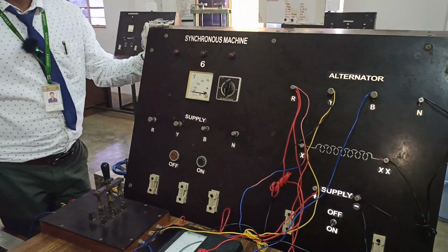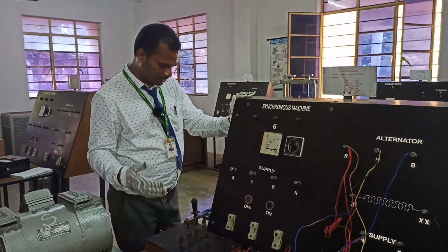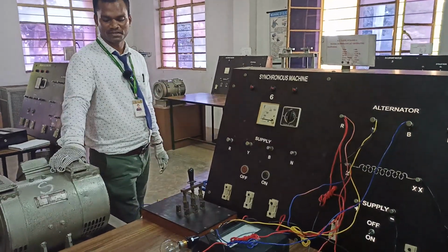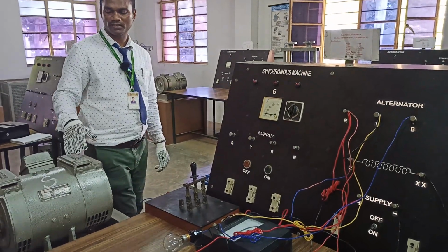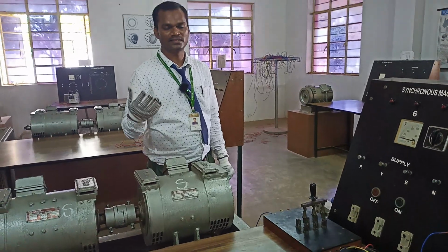In a further experiment, we will try to replace this alternator with a permanent magnet synchronous motor, and we are going to find out the regulation of this alternator. After finding the regulation, we can check how to use this alternator for EV applications, while accelerating as well as while decelerating.